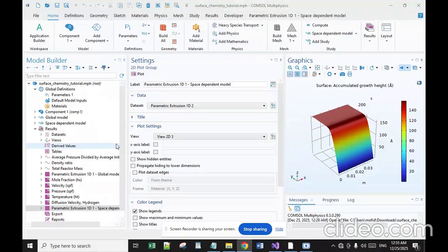And what about the silicon dioxide? Silicon dioxide, usually called simply oxide in the semiconductor industry, may be deposited by several different processes. Common source gases include silane and oxygen, dichlorosilane and nitrous oxide, or tetraethyl orthosilicate, and these have various reaction byproducts.